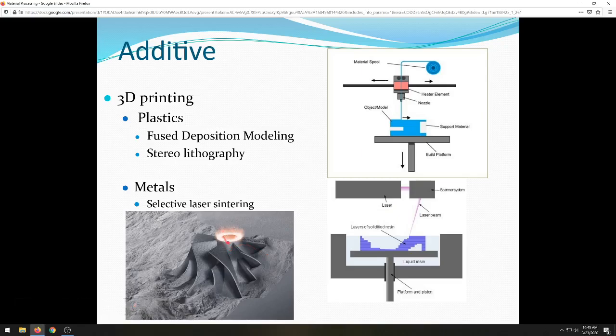And then a laser goes over layer by layer and builds this thing up. A layer of powder is raked out by the machine. It gets lasered in the area where it needs to be printed, so to speak, where a layer needs to go. The laser melts the powder so that it forms a solid. And then the next layer is raked out, and so on until the product is built from the top up.